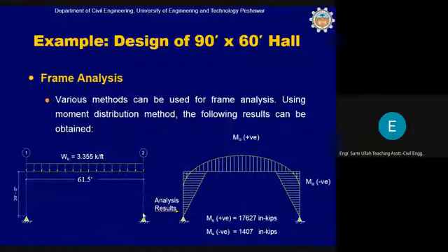Several times you would have analyzed situations like this. So you can use any method of analysis for this, but you should use an exact method of analysis. Now you can't use the simple approximate method of analysis for this. You would have a positive bending moment and negative bending moment like this. Okay, you know how to do this using any method of analysis, stiffness or flexibility.